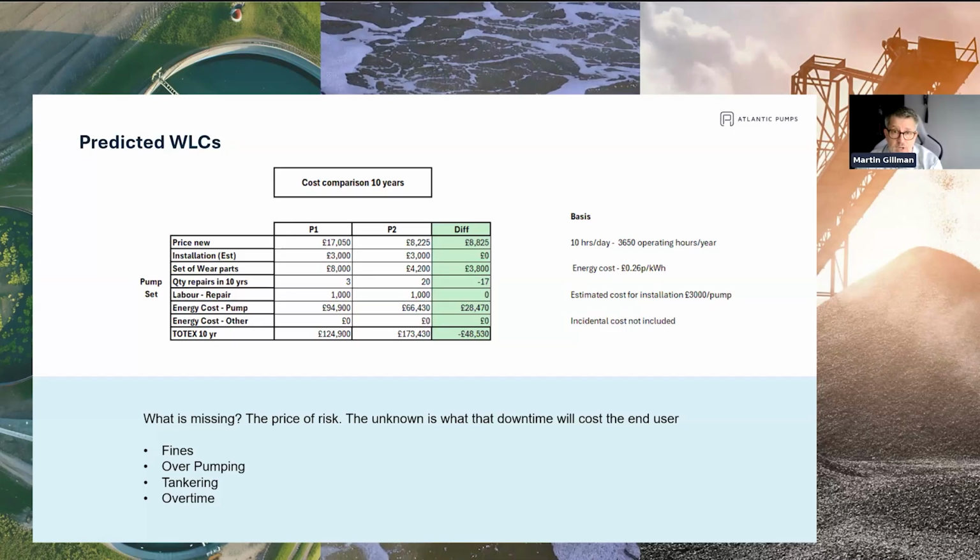Whole life cost sheets are a guess at best. Any manufacturer should be open to you about that. All the tests are done on water on the test bench. You're pumping very abrasive, thick sludge. They're very different things. You'll get a very different response out of the equipment. Energy: yes, a lot more energy is being burned.